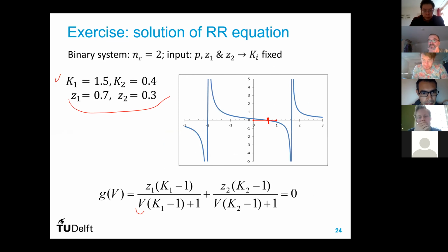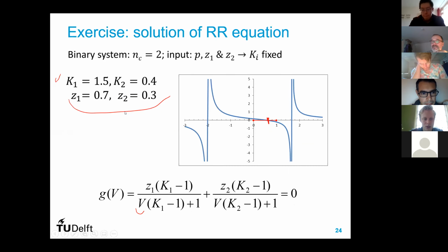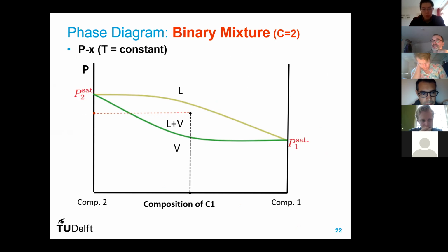Returning back here, you have all kinds of geometrical rules to define yourself. The logical rule can depend on evaluation of dew and bubble point pressure, or you can do the same trick with the dew and bubble point temperature at fixed pressure. And then compare where your pressure is for the given composition. You can do it for two components. It can be done for any number of components. It's the same. You cannot just plot it here, but it's the same rules.